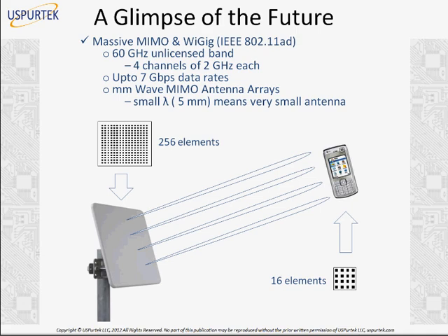You get a phased array the size of a pizza box with multiple independent elements. Of course, here the frequency is 60 gigahertz. Currently, there are some applications where we use this high frequency for wireless backhaul. Wireless backhaul means when you connect a base station antenna to the core network, you use high frequency because you need more bandwidth. You have to carry so much data from different users connected on the wireless network that you need a high frequency to carry all that bandwidth.